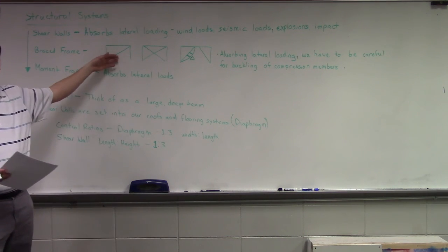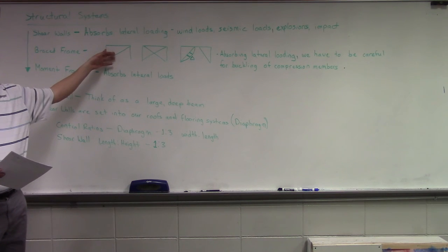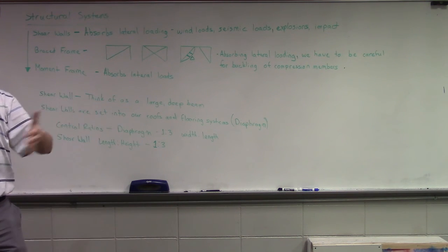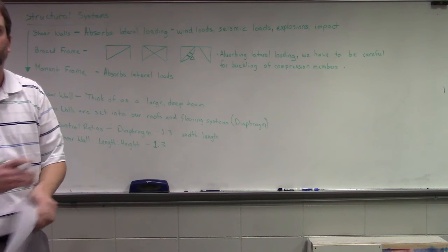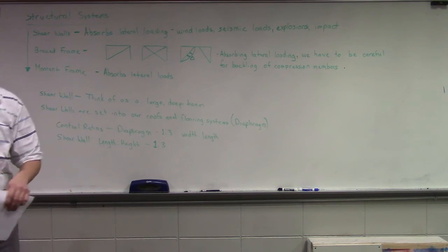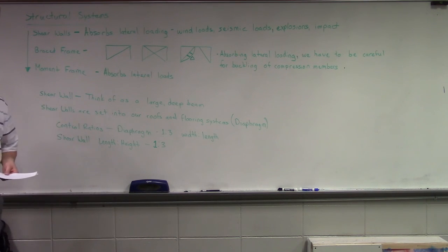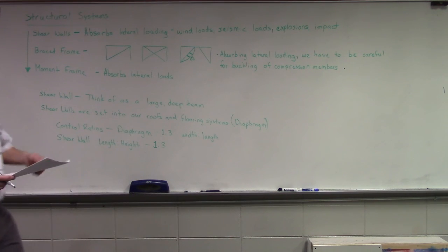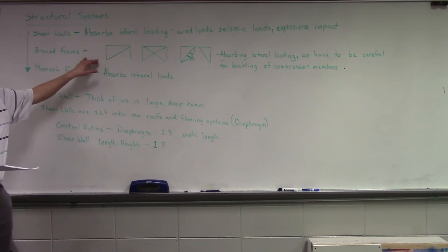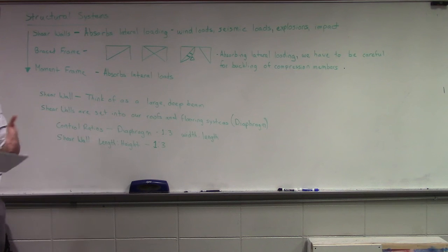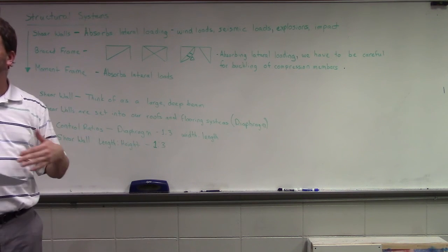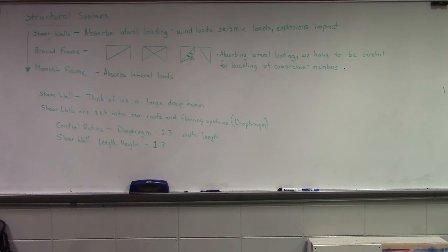Isn't that all a truss is when we're doing truss analysis? We can then turn it into a large, deep beam, and now we can start doing analysis that way as well. Okay, so you can use all those skills that you used in analyzing trusses to help you with either a braced frame wall or in a roofing system, a floor joist system, anything of that nature. Okay?